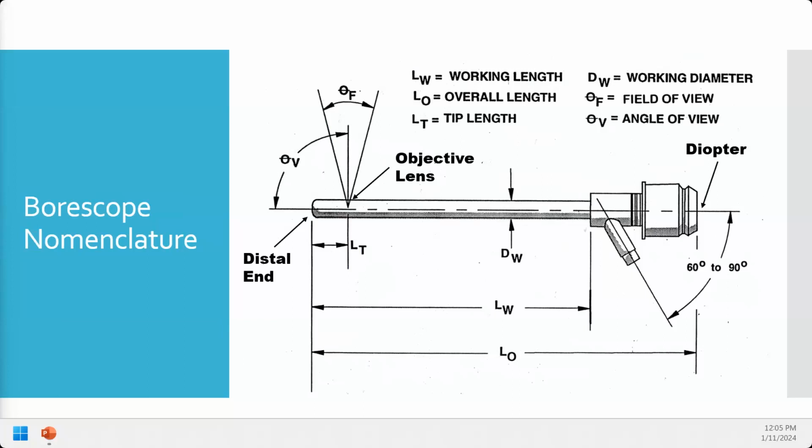It has this sleeve that goes onto it. It turns that into a 90-degree angle of view. So now when I put the sleeve on, I'm either looking straight up or I can look straight down, right? But it's the angle it makes with the center line of the scope that we're looking in. So this is 90-degree, 0-degree. This skinnier scope that I've got is a 90-degree angle of view. So you look down the end of it and the center of your view is straight up or straight down, 90 degrees to the center line.